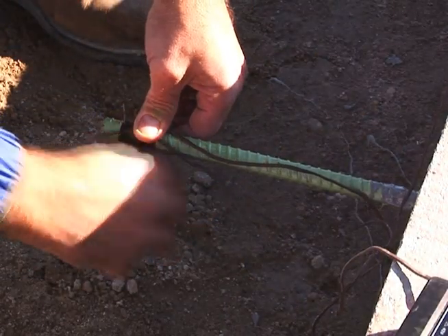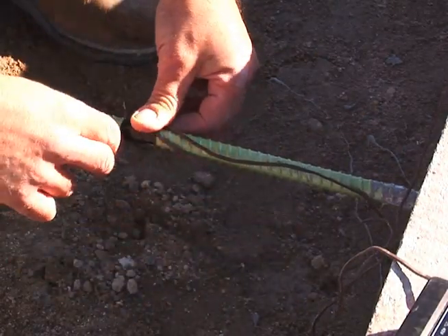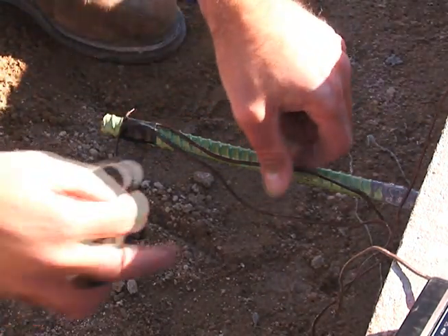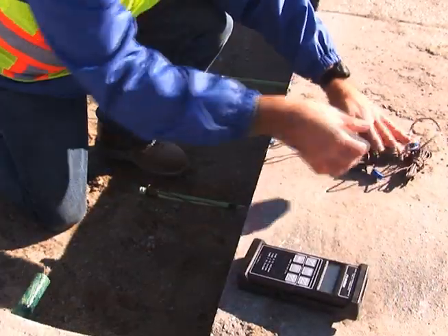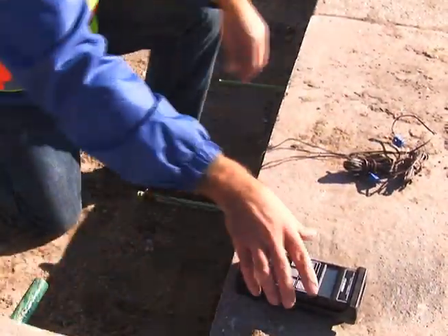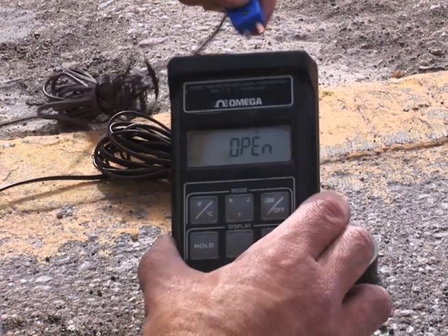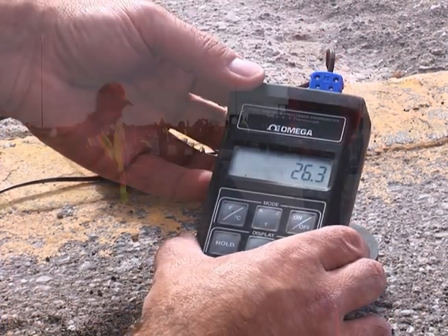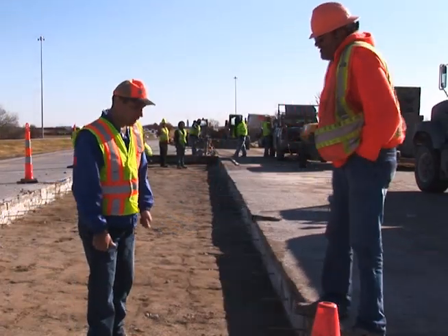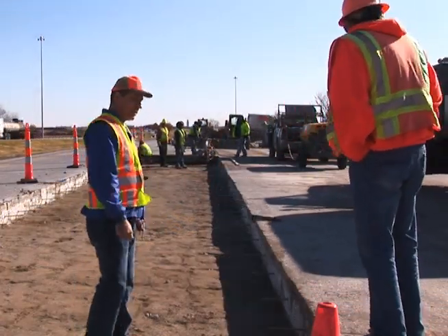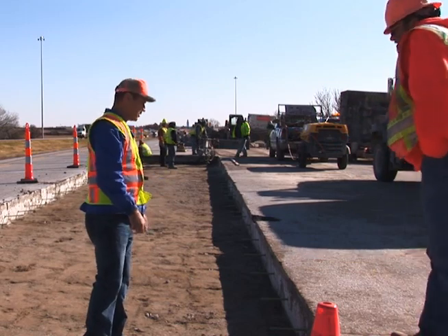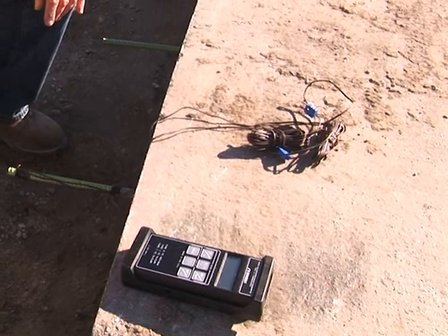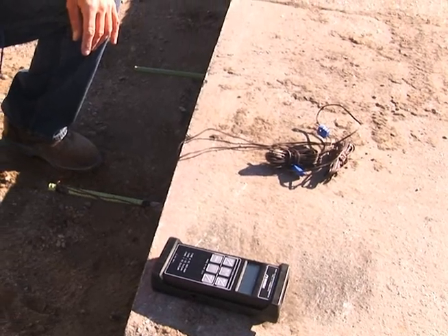The most common installation method is by attaching the thermocouple wires by tying or taping them to an existing tie bar or dowel bar in the removal area. Run the wires onto the adjacent slab of the removal area. Test the wires for conductivity by taking a temperature reading with a monitoring device. Once the wires have been tested, it is recommended to take measures to protect the wires and connectors from being disturbed. This may be accomplished in several ways, not limited to the examples shown here.